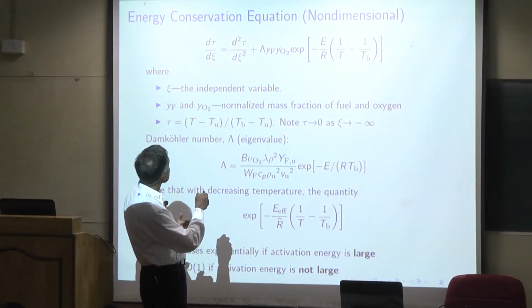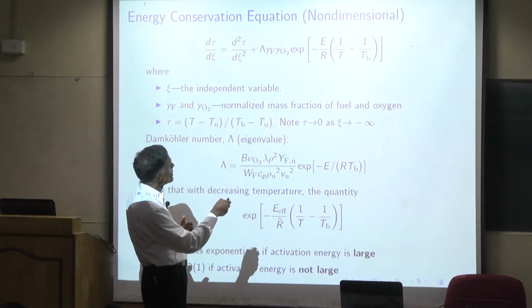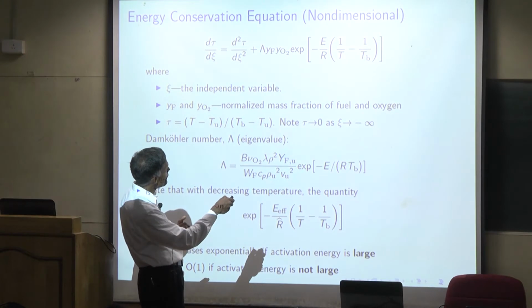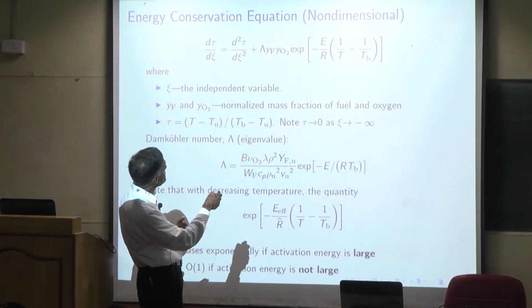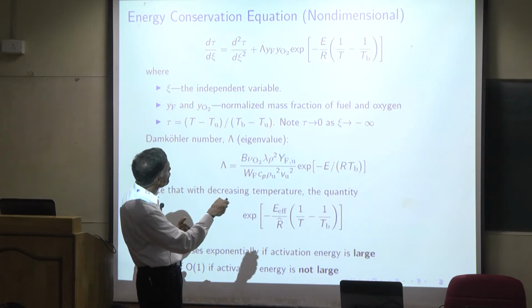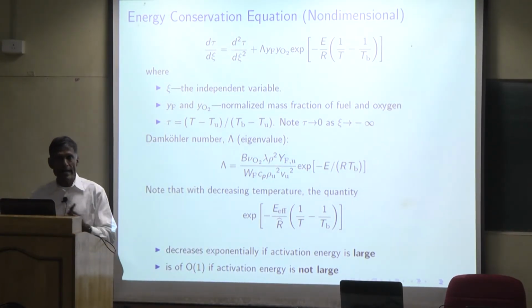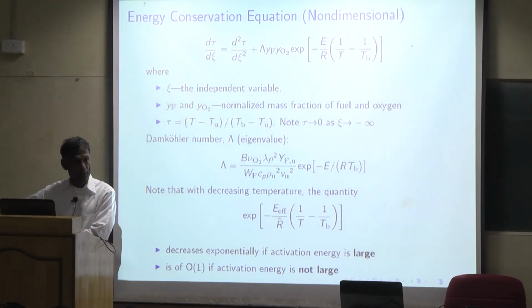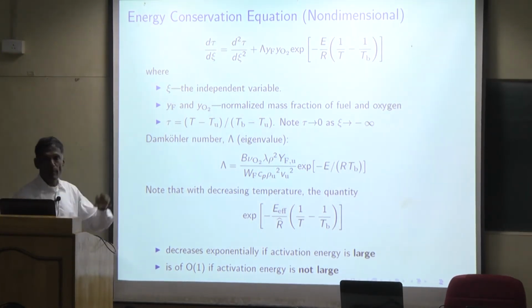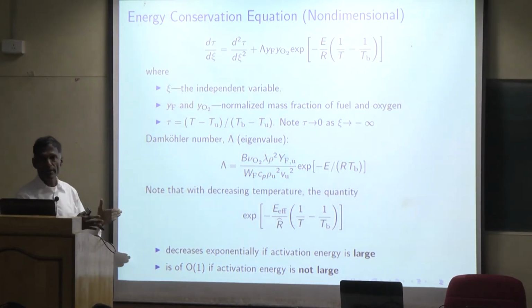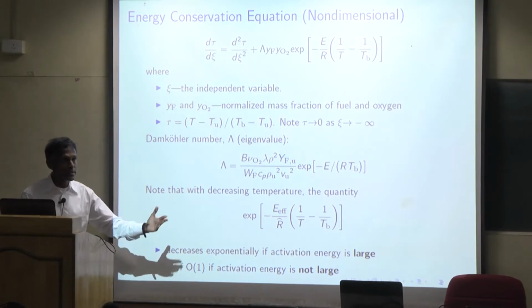So now it tells you that this is 0, this is 0, but this is a finite number, because I know the initial temperature, so I can put a TU over here, and I know what TB is. I can estimate that. So that is the problem: this equation is not balanced. At minus infinity, it doesn't work. So mathematically, it's not properly posed the way it's written. That is the central issue in laminar flame theory, this so-called cold boundary difficulty. The equations do not satisfy the cold boundary.